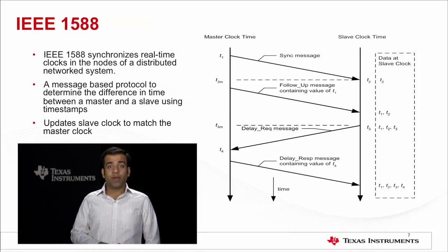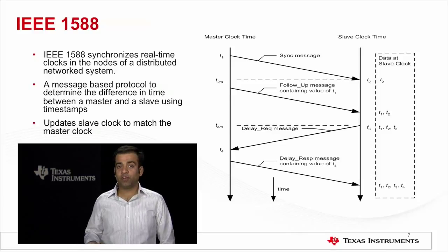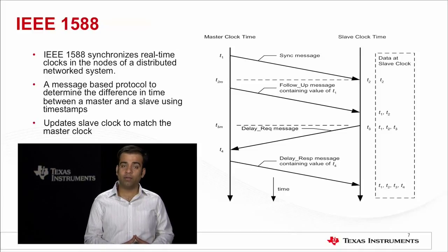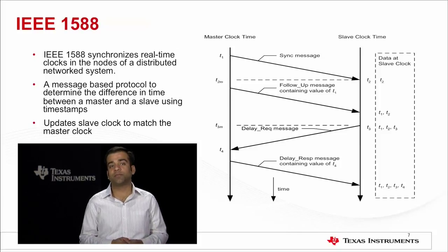The protocol works by exchanging time-stamped messages between nodes and uses the delay determined by these timestamps to update the device clock. This update occurs on a regular basis. The precision of the system is set by the amount of error induced into the timestamps. This error can be reduced by capturing the timestamp closer to the wire. This standard replaces expensive coaxial timing cables for Ethernet-based control and measurement system.